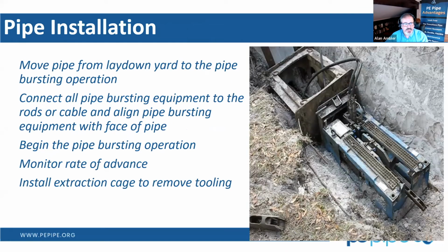Moving that pipe from the laydown yard. I try to look for possible laydown yards at the max a mile away from the site. Sometimes we don't have that luxury, but the actual timeline to be able to move a pipe string from the laydown yard to where you want it to go in the pipe insertion pit sometimes doesn't take that long.